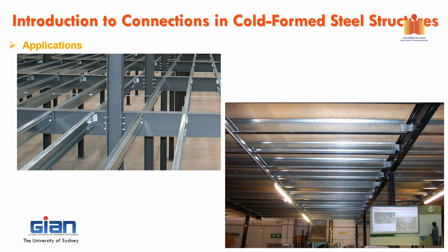Okay, so I draw it and you've got an I-beam in here. Is that right? But when you connect to the column, this beam is somehow another big one. So in hot roll, you can always easily cut that one. What you call is a coping. You cope that one in order to fit our beam here, a bigger one, right? And then you've got a tab and you just bolt it somehow.